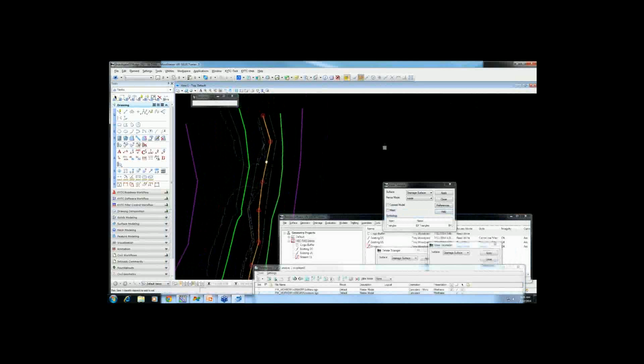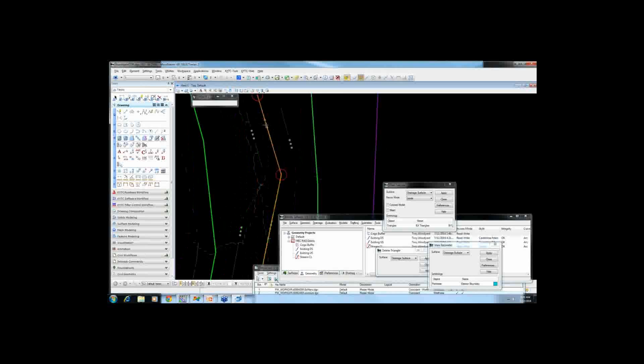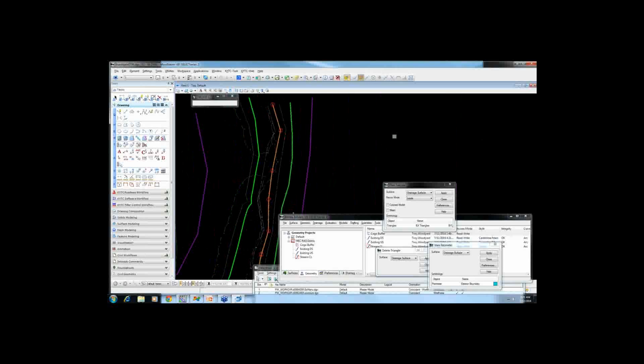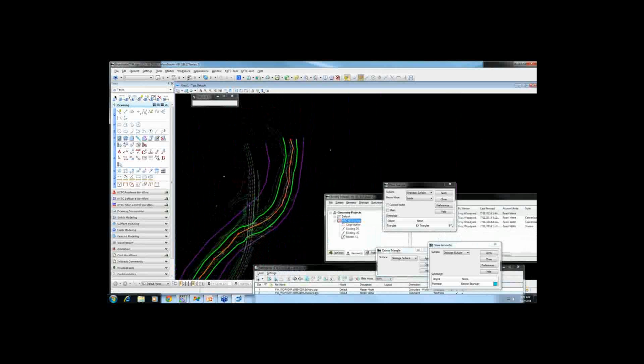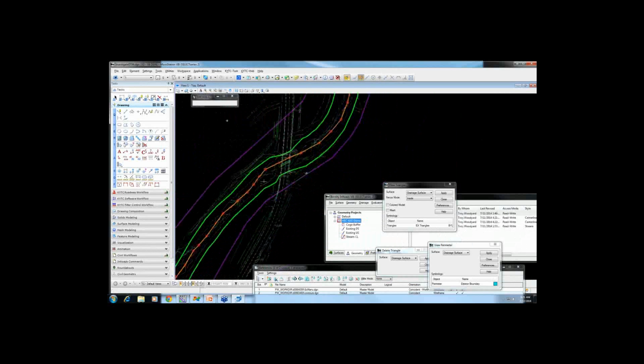So I just use the geometry horizontal curve set tools, add PI, and traced the surveyed center line of the stream from downstream to upstream. And I cut off a few of the meanders, like right here. All that would do would be to lengthen the distance between a cross-section here and a cross-section here. And that's not really accurate when you get to flood stages.